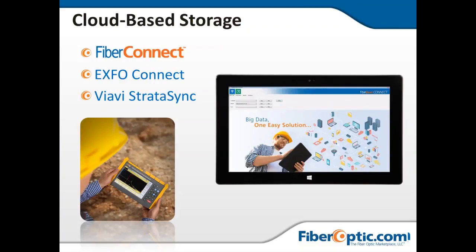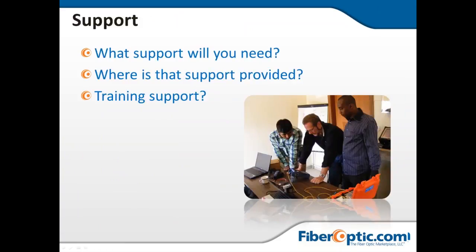It'll be a straight line immediately, but then you can go back into the full Fiberbase application, not through Fiberbase Connect, and you can actually draw the conduit path and then drop and direct the fibers to follow the path that it actually does follow in the field. This makes troubleshooting in the future much easier, because an OTDR will show you where loss occurs, but if that's not mapped to a physical GPS coordinate, all you have is distance, and you're going to have to drive that distance until you can figure out where that is.